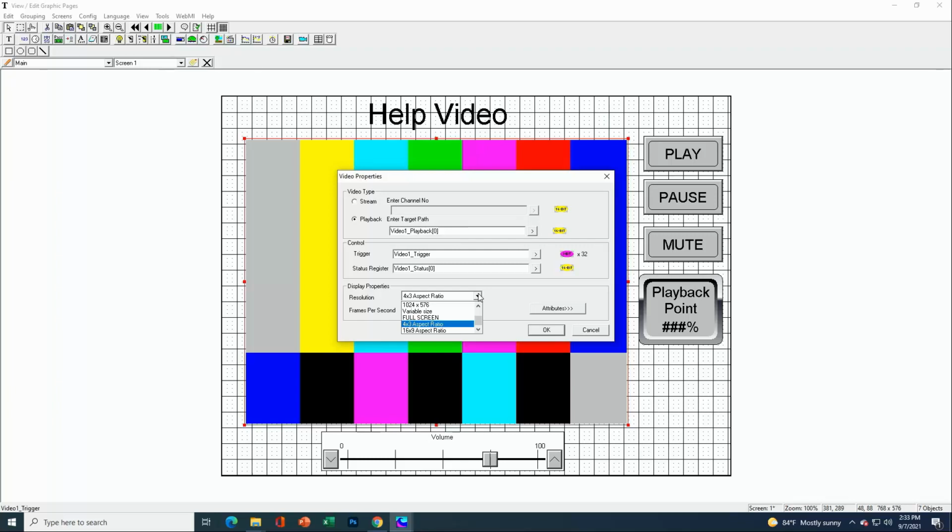Okay, so pretty flexible from a configuration standpoint in the case of the XL Plus. The other big difference here is that the status register is no longer a single 16-bit value. It's actually 3 consecutive 16-bit values. So that's why I've assigned a word array with a dimension of 3 for status in the case of the XL Plus. Another thing to see is that even on the trigger register, that's no longer an integer. That is now a double integer value. Okay, so again, with more control comes more of a need for additional control bits and additional control words. So those are the main differences in the configuration of the XL Plus versus the configuration that we just reviewed in the X5. Everything else is very similar.